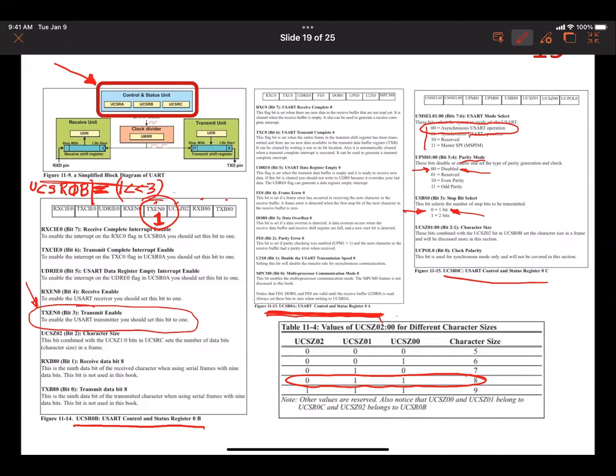I mentioned before that we have to look and see whether the data register is ready or not. So there's a bit here that we're going to have to be polling. We're going to have to keep looking at that register until that bit goes high. That'll tell us that this data register is not busy. So I'm just walking you through some of this stuff. I'm going to show you in more detail and with actual code how you do this. The reason I'm walking you through this is that I'm going to give you the routines for everything that we're going to need in the course.